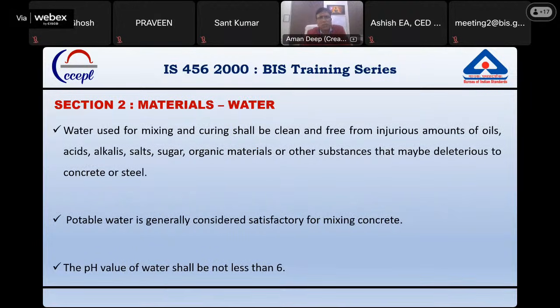Now, section 2, again for materials, we talk about water. Water plays a very important role in the quality of concrete. Generally, we add water for two purposes. First is the hydration of cement, to make the cement a glue or binding material, and some free water is also added for the flow requirements.